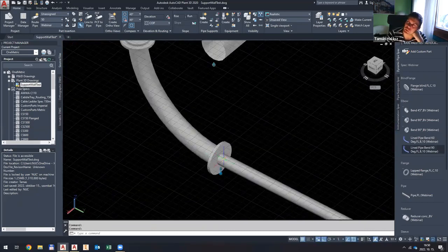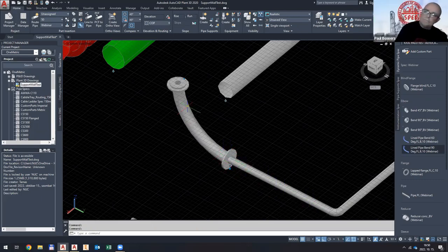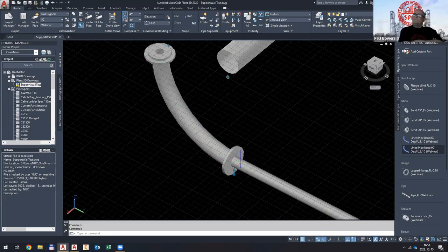This is actually, we are using it for pneumatic conveying. You know, we are conveying sand-like material, and when there is a direction change, you have huge abrasion. So these kind of pipes are ceramic or basalt lined stuff. That's why it is having this bigger diameter, because it is having some 25 millimeter or 1 inch thick ceramic lining.